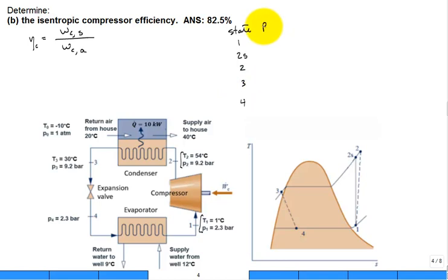And then I like to put pressure in kPa or bar, the temperature in degrees C. Some quality would be for state 4. That's where the quality is needed or used to check things. And then the enthalpy in kilojoules per kilogram and the entropy in kilojoules per kilogram Kelvin.